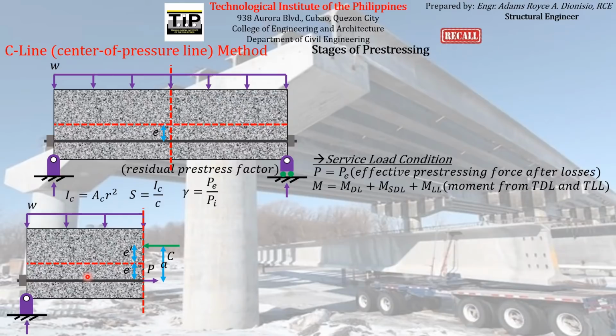If you can recall from statics, if our element is in equilibrium, then if you sum up all of the horizontal forces acting on it, their sum must be equal to zero, meaning there is no tendency to move along the horizontal direction. The only horizontal forces acting on this left segment are the total compressive force and the pre-stressing force acting on the pre-stressing reinforcement.